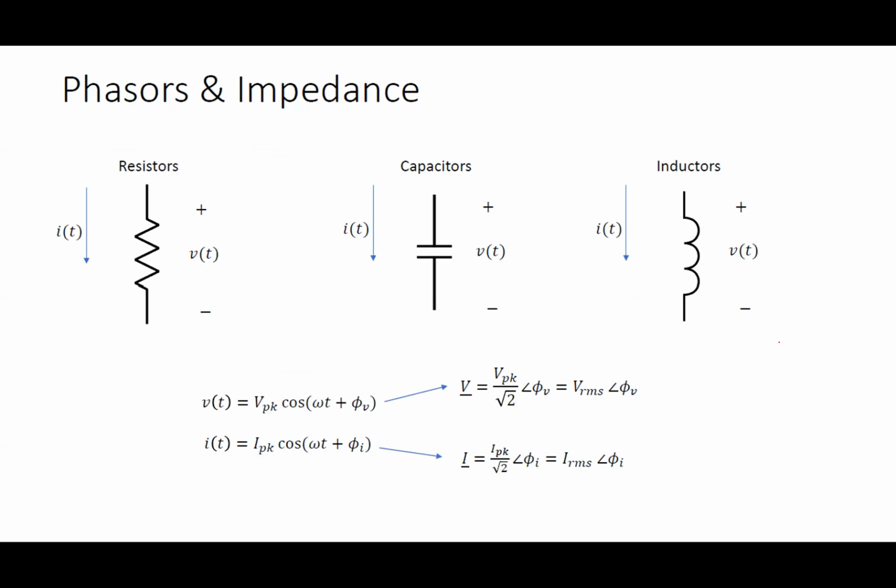Before we get too far down that road, let's remember impedances, because you said sL. We don't usually use s here; we're going to use jω. As you'll find out, in the power world they often don't use L. What they actually use is X. X is omega times L. We'll talk about that more.